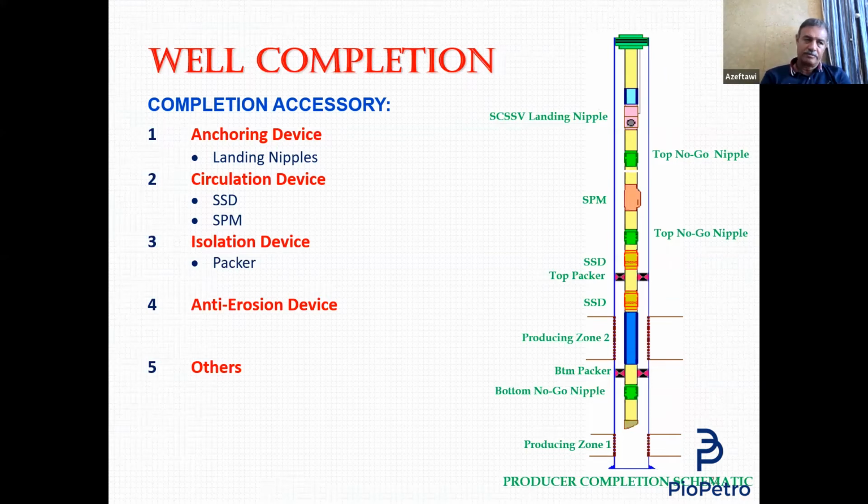What hangs the bottom completion? It is the packer. Then if I give you in the exam a question, what's the purpose of the packer? And you select the answer saying to hang the bottom completion, I'll give you a big 0, because the packer is doing that as a favor. It is not in its job description to do that. The packer is to isolate. Isolate what?